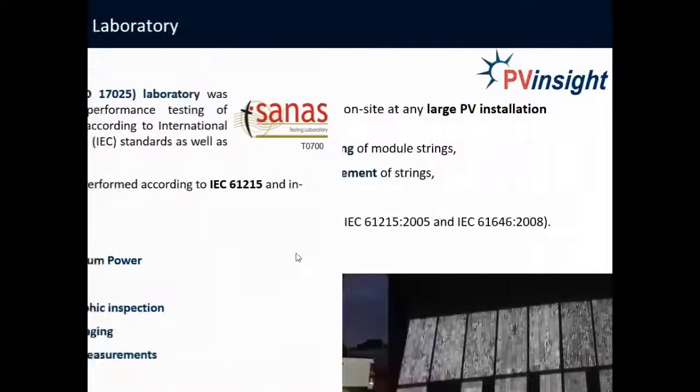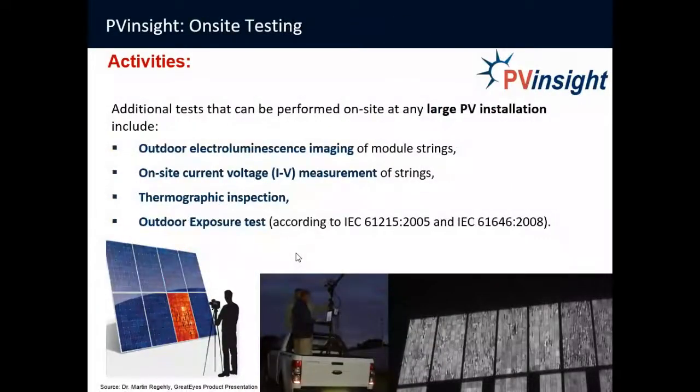In addition to the lab-based tests, there also are on-site tests that can be performed on large PV installations. This includes outdoor EL imaging of modules and strings. In the corner of this slide, you can see an EL image of a module string, indicating where there are problems in the modules.